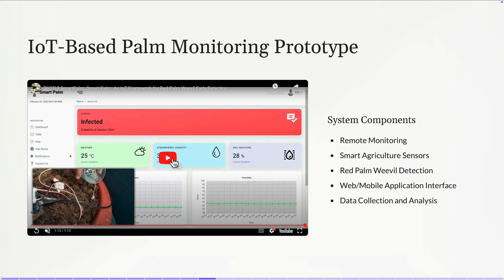Yes, that's another challenge, because you must have all these sensor devices connected to the internet so you can monitor them. So you need to have energy close to the farm, you need to have internet connection, you need to have network coverage, and you need sufficient range to send the information, because usually Wi-Fi sends you 10 meters, 20 meters maximum, maybe now 300 meters, but you can have farms kilometers away. And this is why we need different types of communication approaches.